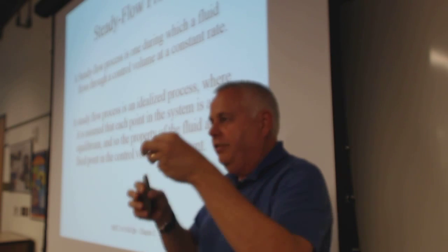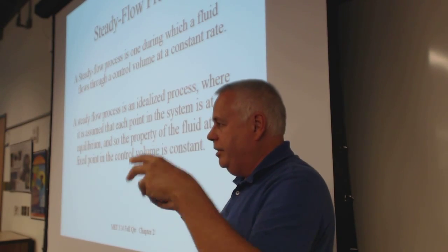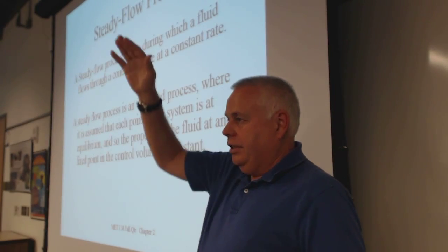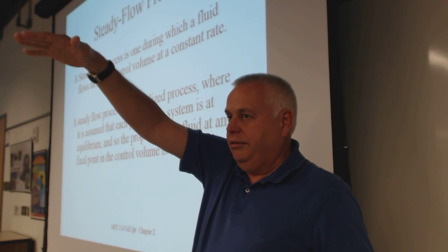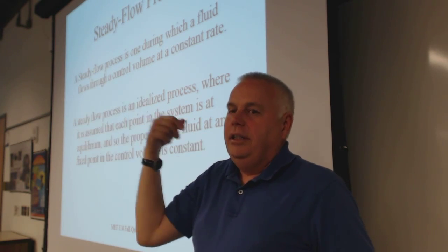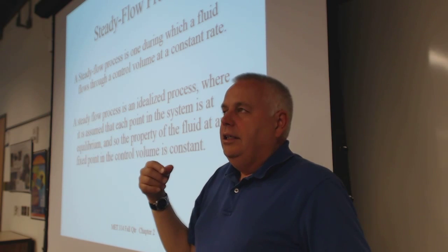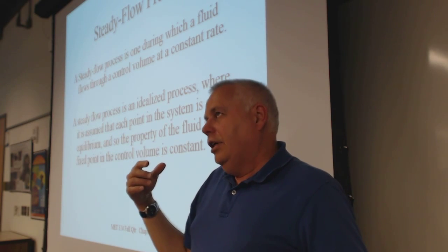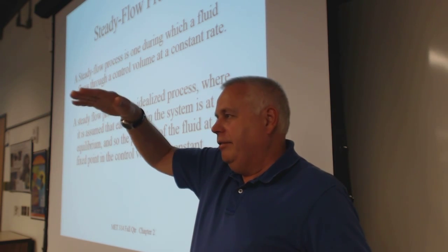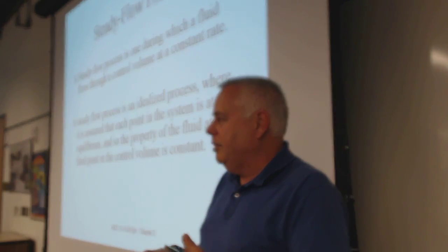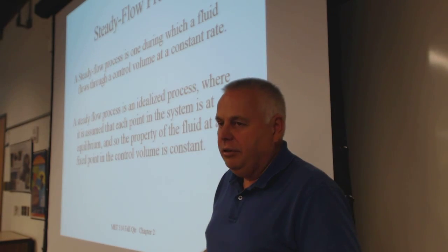You have the same amount of stuff coming in and going out, and it stays the same with time. That would be after the jet gets up to altitude and is cruising for an hour at the same speed. That's steady. Not immediately, but give it a couple of minutes, and it will be in equilibrium and stay the same as a steady flow process.